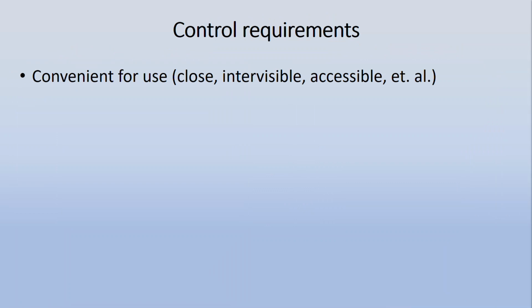You know, a total station can easily shoot over a mile now to a prism, but you have to balance the ease of that data versus the accuracy of that data. And just because it can shoot that doesn't mean you should be using the data. It also has to be accessible.